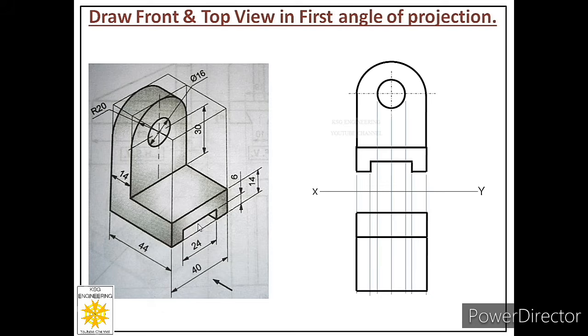Now these three hidden faces are hidden below this particular face because we are looking from top. Or we can say this face is divided into three parts. That's it. If we will represent for this middle face, other two faces will automatically be represented. So or otherwise if we represent these two faces, then third face will automatically be represented. So in order to represent this face, what we can do, we have to show this edge and this edge of the face, which is hidden below this face.